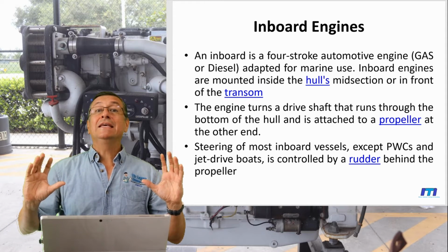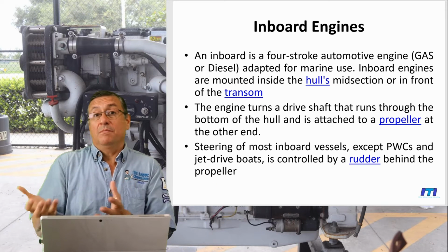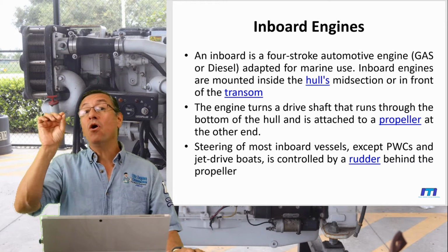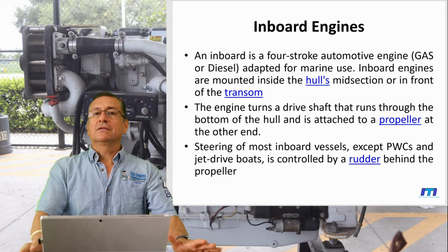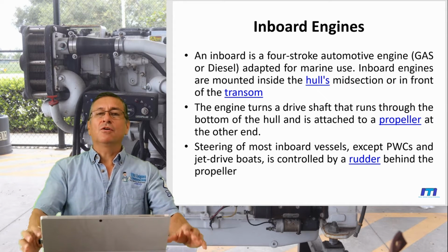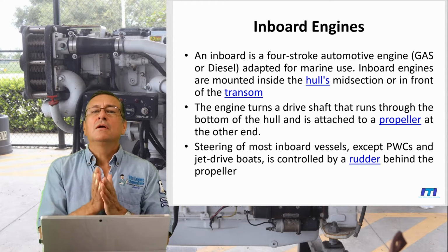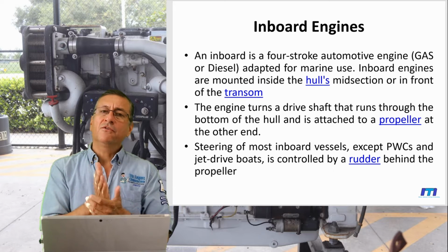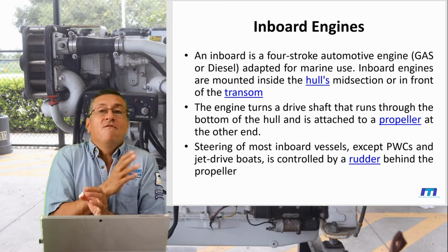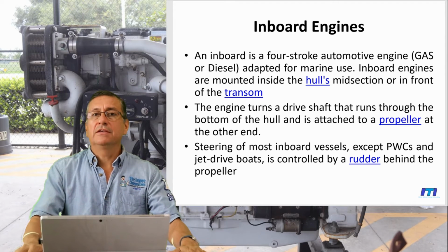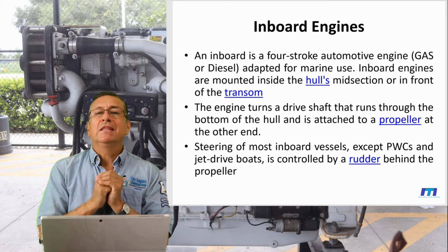The only difference is the cooling system and the exhaust manifold, because we need to replace the exhaust manifold to receive the water at the end and send the water with gases outside. That's too simple. This is not complicated. I am going to explain the procedure step by step in order to repower the boat from gasoline into diesel, and convert the boat now to a diesel engine. There are a lot of tips that I am going to use to do that project.